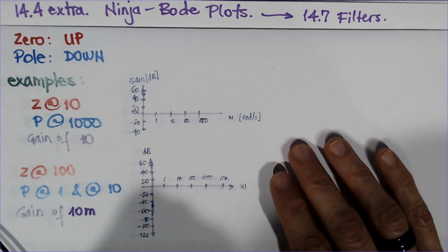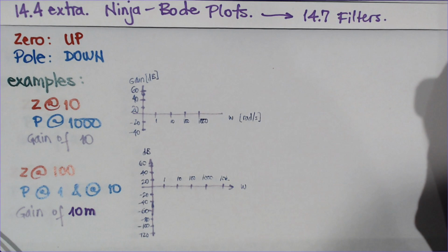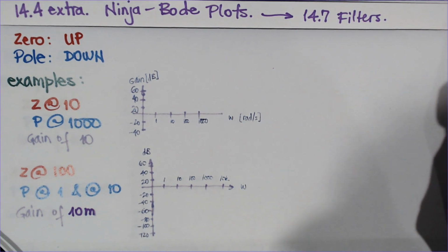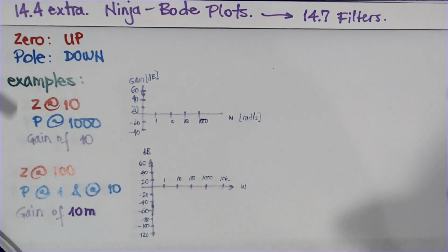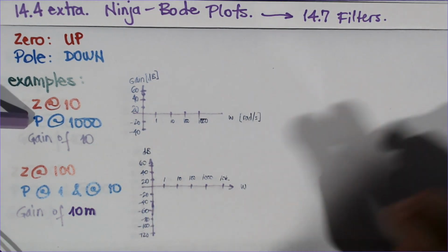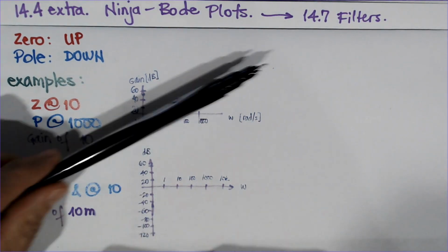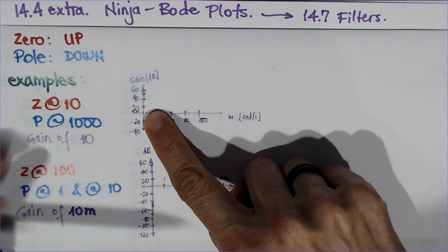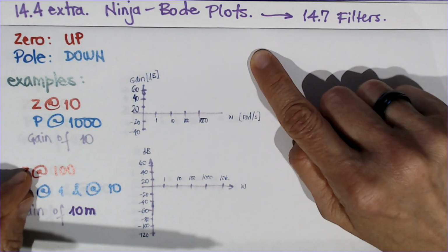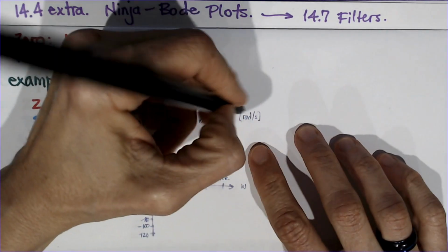Of course, you can continue to watch those videos on how to make a really nice Bode plot. This is a job interview question again. It's like, I will give you the gain, a 0 and a pole, draw the Bode plot without thinking too much. So let's remember that a 0 makes the Bode plot go up, so the gain for omega tending to infinity will be super high.